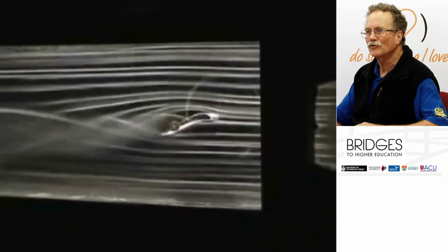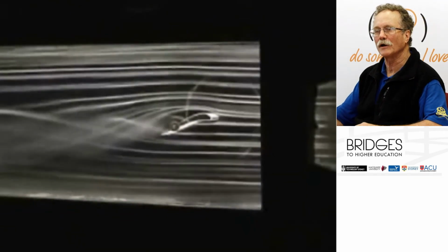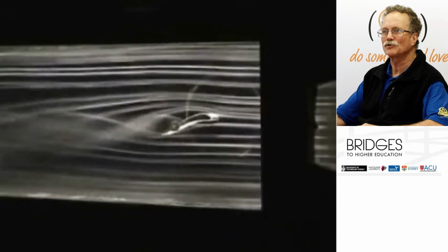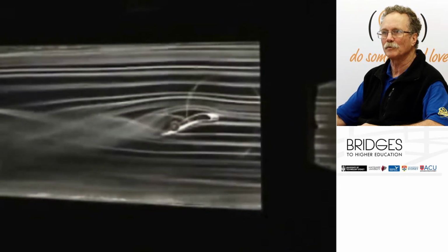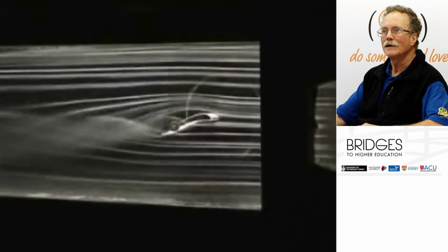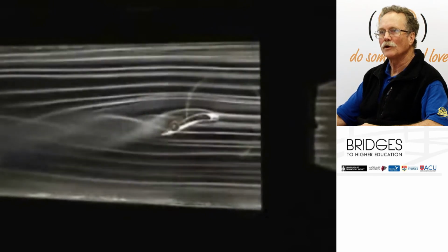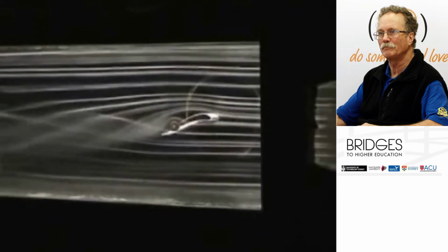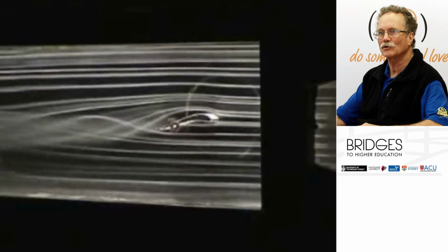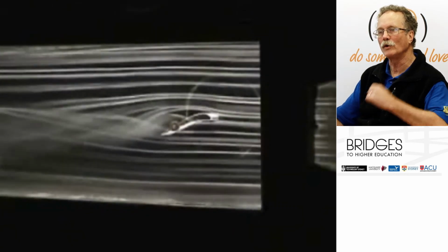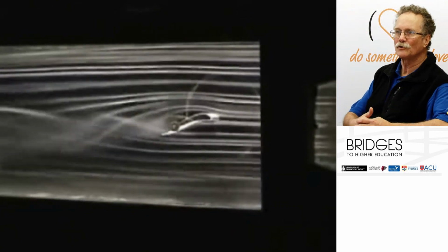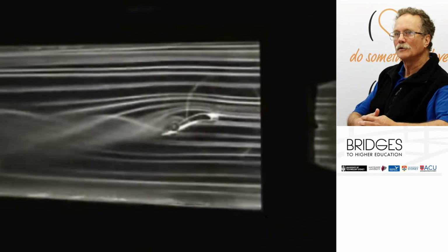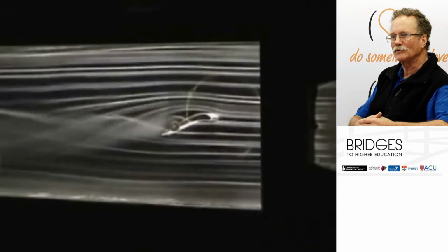The aim of a winglet is to try and reduce the size of that rotation. So this is just a straight square tipped wing. This is a typical example of an inefficient wingtip. With the winglet, what you can try and do is adjust the angle of the winglet to reduce this spinning. This spinning is the thing that produces the extra drag component. So a winglet is designed to reduce the amount of spin, therefore to reduce the amount of tip vortex drag.